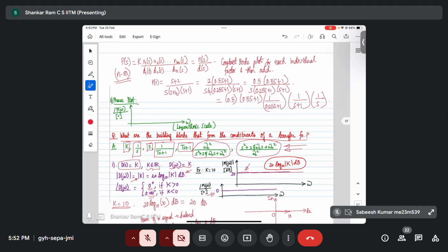Thank you so much, sir. Sir, one basic query from our side. We are essentially saying systems are BIBO stable, right? In that condition, I'm just trying to articulate my question. Maybe I'm wrong also, but if we are talking about BIBO stability, then this asymptote condition, which means it is tending to infinity, should not come, right? It is not within bounded input, bounded output, right?